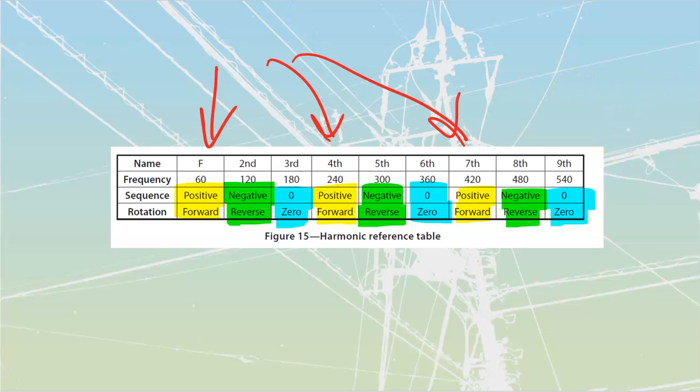They're going to be rotating in the same direction. So what they're going to do is add onto our rotational forces. They're going to cause overheating inside of our windings and our supply conductors, because really what they're doing is adding to what we have inside of there. Just look at absolutely anything where if you stuff additional current through it, even if it's current that's being self-generated, that current is going to cause more overheating. So these ones over here are going to be heating types. Let's put that up top over here.